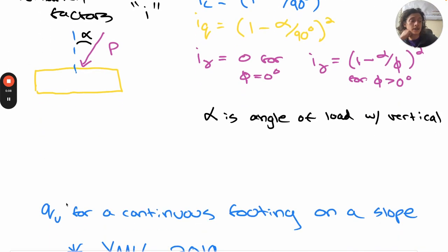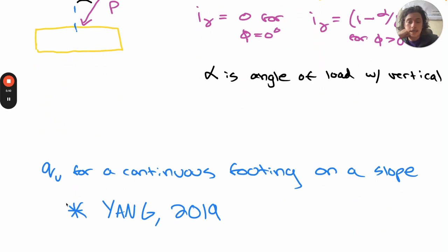So we can calculate all of this out and get a value for a continuous footing on a plane or rectangular footing on a plane. You may notice this is a pretty high value for bearing capacity compared to the IBC values, which are far more conservative. But there's one other step we need to take in further reducing our bearing capacity value, because we need to factor in the fact that these foundations are on a slope.